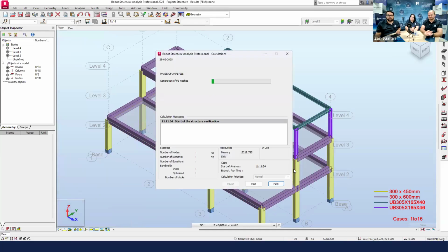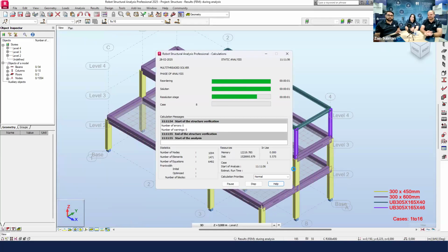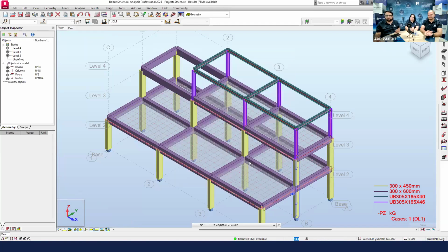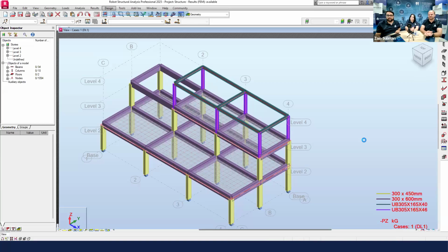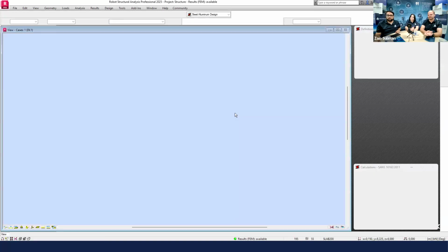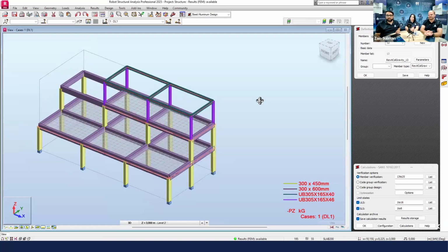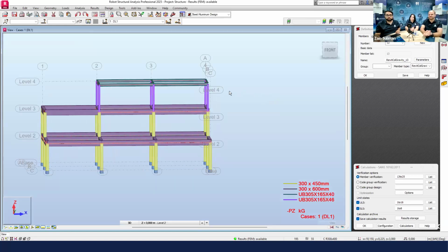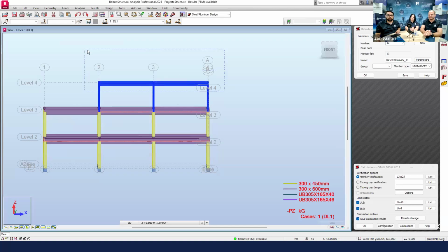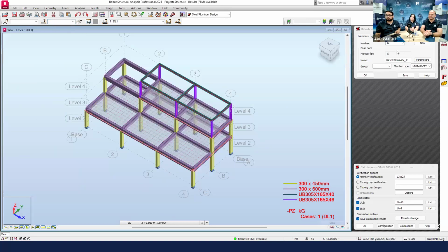First thing, I want to do my calculations, make sure everything in this model is working fine. I have everything fine in my model, so I'm quite happy. I can then go through my design. So this is where I basically specify what loads or what I want to test my steel off of. So if I select all of these members, I can just copy all of the actual reference numbers. I'll create a new group for those.